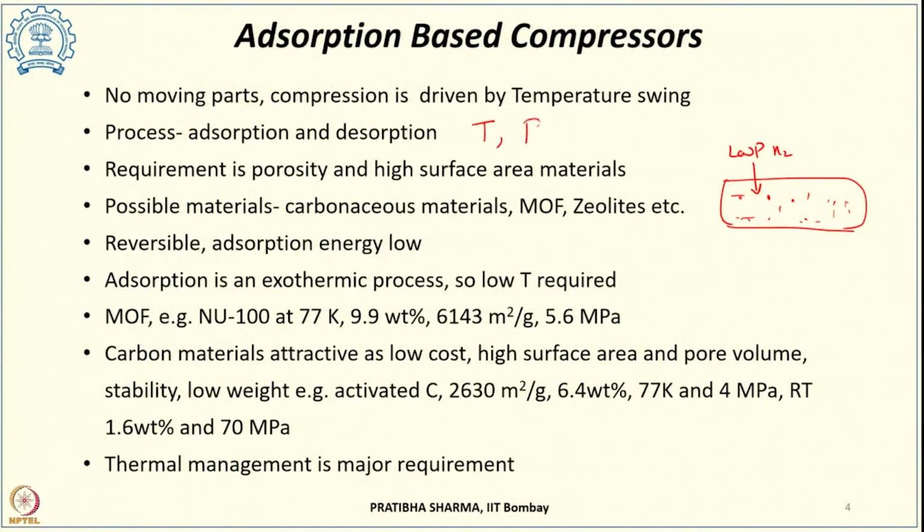Now for desorption, heat energy input has to be provided, which increases the temperature of the system and of the adsorption bed, thereby desorbing hydrogen. Both the adsorption and desorption occur at specific temperature and pressure conditions. Since hydrogen in the adsorbed state is in a very dense state, during desorption the desorbed hydrogen enters the bulk gas phase and that increases the pressure. So the pressure in this way is increased.